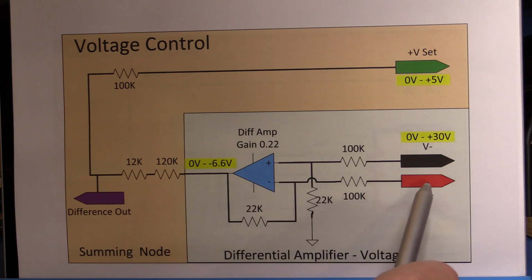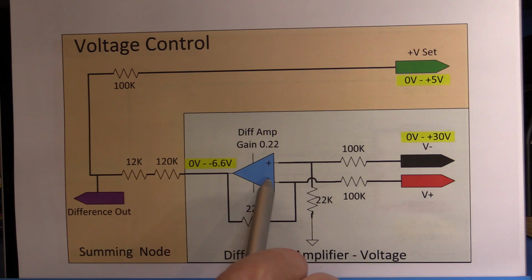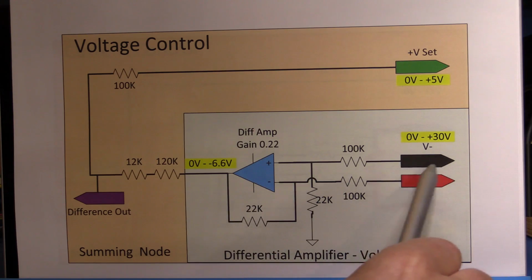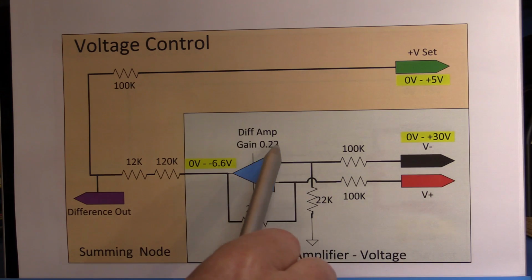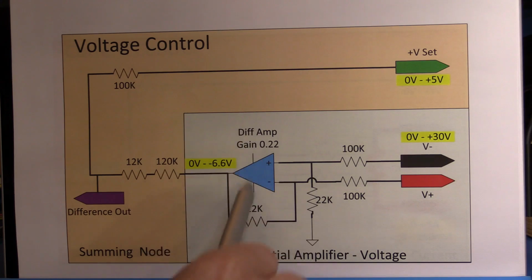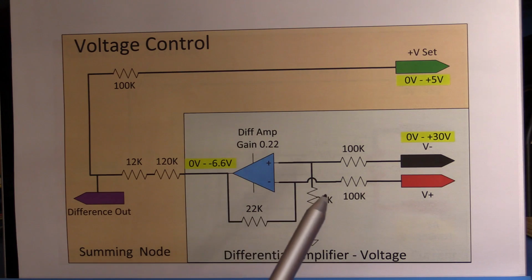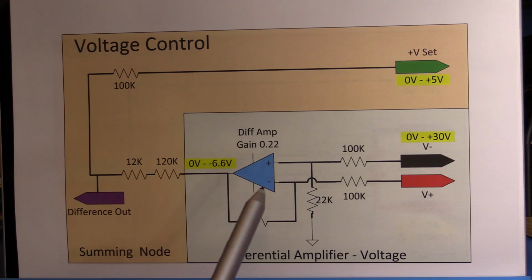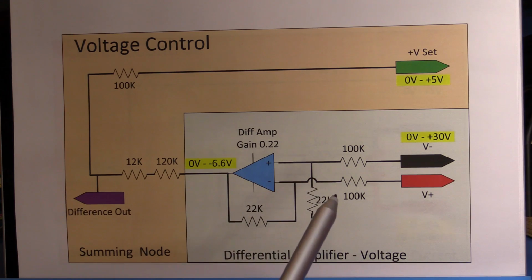Now when you look at this diagram, you'll see that my positive input is actually going to the negative input of the op amp, and the negative input of the power rail, i.e. the 0 volts, is going to the positive input. Now that's perfectly fine for a differential amplifier, and remember, we're going to be driving this amp with plus or minus 12 or plus or minus 15 volts or something like that. Just a standard off-the-shelf kind of split rail supply that you can get relatively cheaply. You can make it with a transformer and a bridge rectifier, a couple of caps, and some low-cost 7812, 7912 kind of voltage regulators will be more than adequate for this.